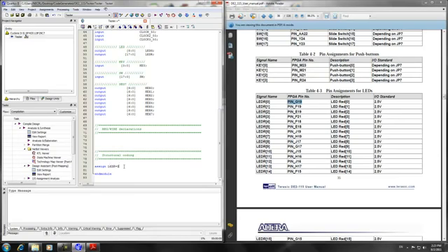For this example, we will assign all of the red LEDs to the switches. So every time we turn the switch, the corresponding red LED turns on. We assign the green LEDs to the keys to use only the last 4 green LEDs from 3 to 7. Every time we push one of the keys, one of the green LEDs turns on. We use the tilde because the keys are active low.